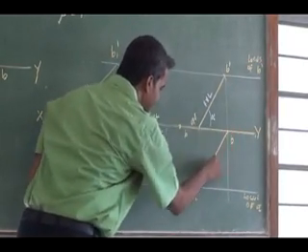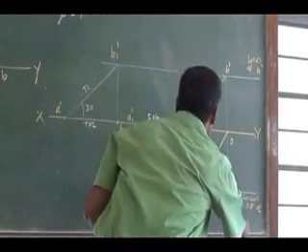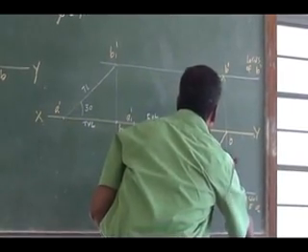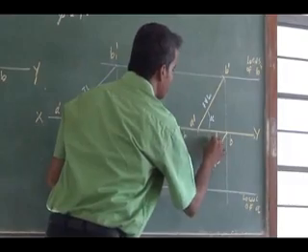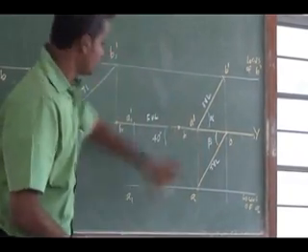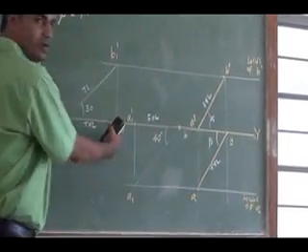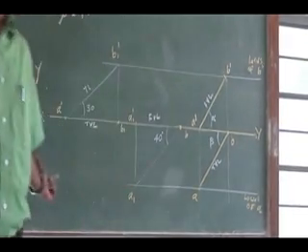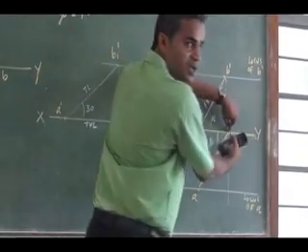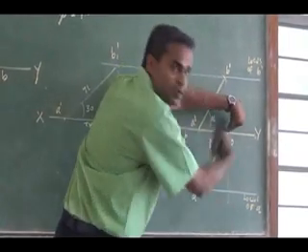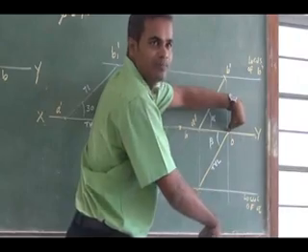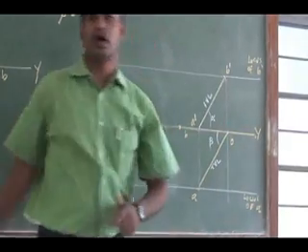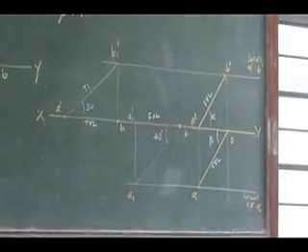You can cross check what this length should be. This is my top view length. This is going to be my beta. This top view length has to match the top view length you got from the first step. Otherwise, you can mark B using the top view length, cutting it to the bottom locus. That will coincide; it will fall on the same projector line.